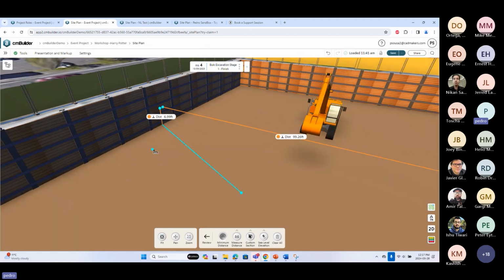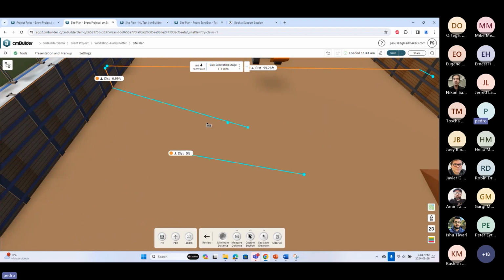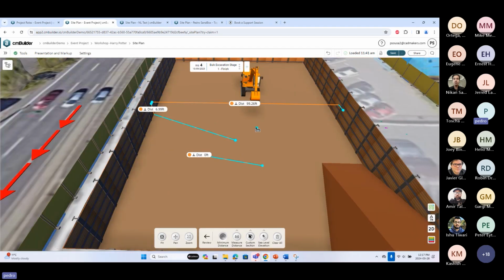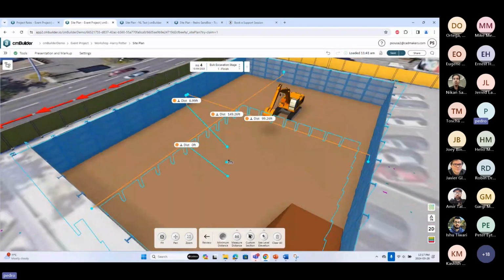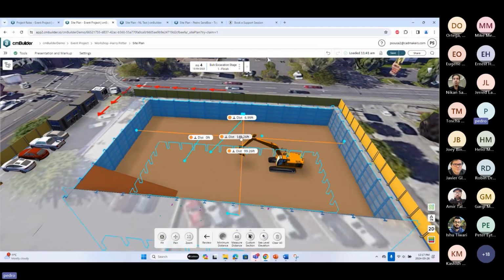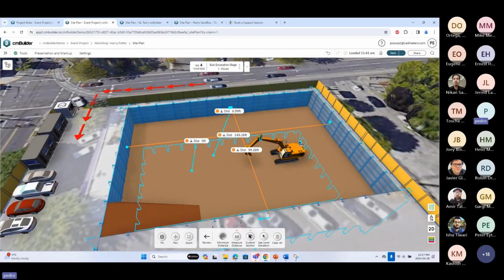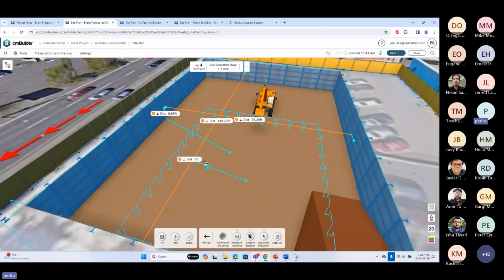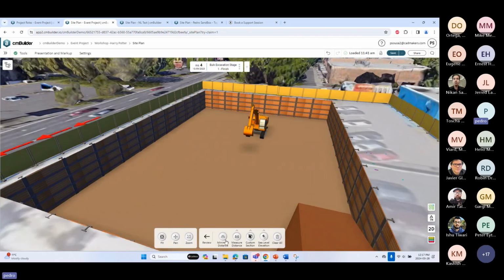If I make 2 measurements on the same surface, there will be no distance because they are contained on the same surface. Okay, so this is a way for you to quickly measure, especially things like width, height, and so on and so forth, without having to find exactly which point it is that you're selecting. This is a fast way for you to get those distances. Okay. And whenever you start making these measurements, you can always click on them, right click on them and remove, or you can clear all over here from the bottom. So this is the minimum distance option.